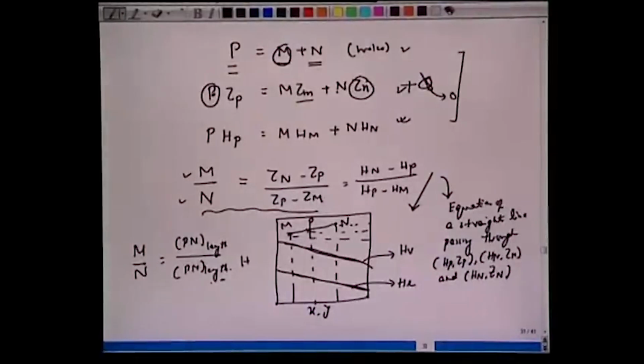Alright, so what we have done so far is that we started with the HXY diagram. We said that just like we have a TXY diagram, we fix the temperature, we know the mole fractions X and Y, pressure is fixed, and the enthalpy of this binary mixture of A and B corresponding to X and corresponding to Y will be fixed. One can calculate it knowing the sensible heat and the latent heat of evaporation. We calculate the sensible heat of the liquid, knowing the specific heat capacity CL, as the temperature is raised for the cold feed from T0 all the way till the saturated curve. So CL into TL minus T0 multiplied by the molecular weight. So you have raised the fluid temperature to the saturated level.